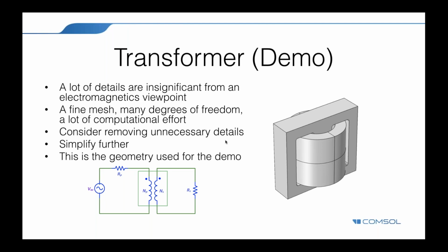So this example demonstrates how to perform transient simulations of a single-phase E-core transformer, including the effect of a nonlinear BH curve in the soft iron core. The model computes the spatial distribution of the magnetic and electric fields, the magnetic saturation effect, the transient response, and the flux leakage to the surroundings. And this nonlinear BH curve includes saturation effects that is used to simulate magnetic behavior of the soft iron core. Hysteresis effects in the core are neglected.